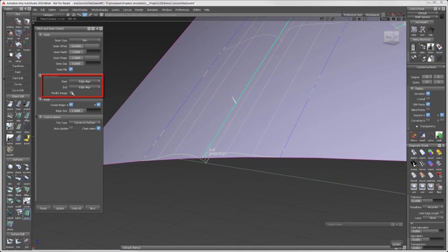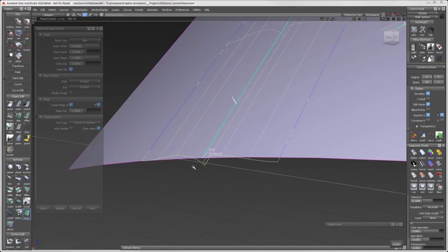With most tools of this type, we can modify the range or adjust the start and end. In most cases, I like using the extend for both start and end to ensure that the surface extends beyond the host surfaces. For seam, offset controls the length of the seam into the surface.